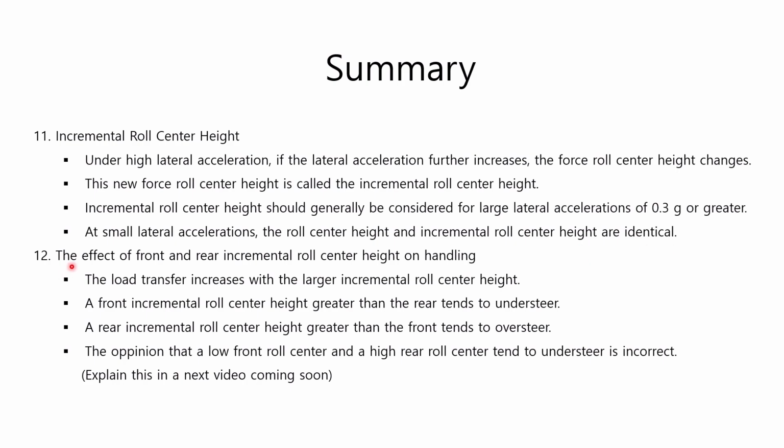When examining the effects of front and rear incremental roll center heights on handling, the load transfer increases with the larger incremental roll center height. A front incremental roll center height greater than the rear tends to understeer. A rear incremental roll center height greater than the front tends to oversteer. The opinion that a low front roll center and a high rear roll center tend to understeer is incorrect. This will be explained in a next video coming soon.